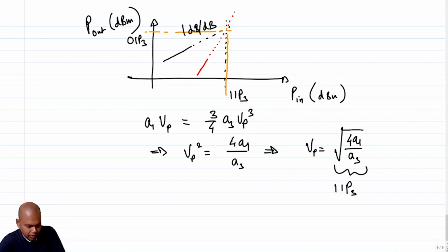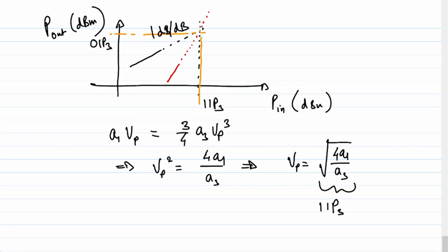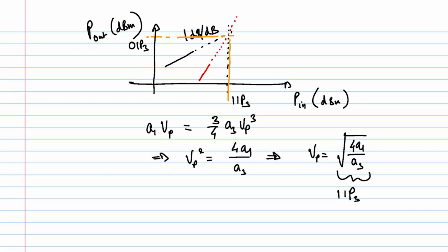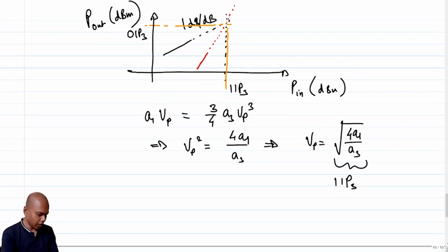Okay. So now in practice, just like before when we were doing IIP2, you will be able to plot these curves, and you can figure out whether your circuit is linear or non-linear by looking at these numbers, right? So you can obviously find out the values of these ratios by directly plotting this IM3 and finding out IIP3.